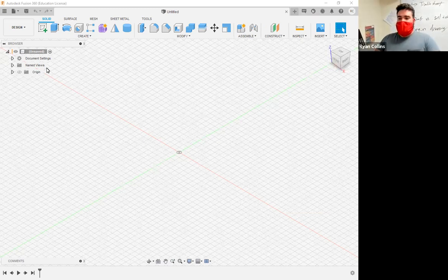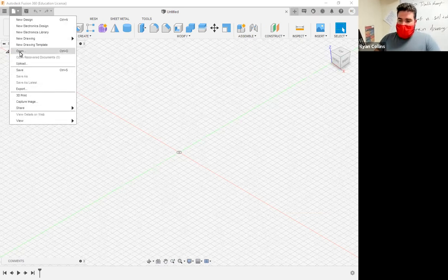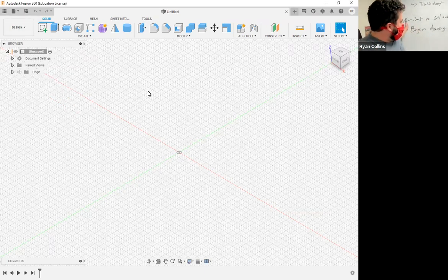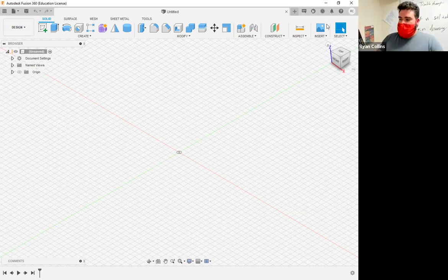And how to get that in, you can upload as standard, but I don't want to do that because, especially with STLs, and this is why there's the whole new format of 3MFs and using object files, OBJs, versus an STL. STL files do not retain information like scale. So often enough, when you import an STL into Fusion using the actual import function, it throws the scale off big time. So what you should do is instead go to Insert.